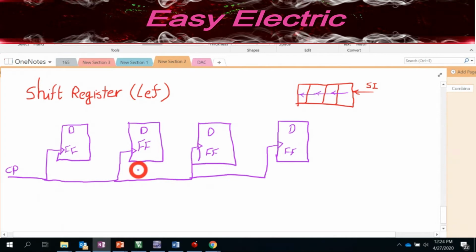So what we need to do for each of these inputs, so the D flip-flop has one input. Whenever there is a rising edge, if this is 0, the output will be 0. If this is 1, it should be 1. Somehow it keeps whatever you give as input, right? Based on what you want to design, the serial input should be entered from the most right one. So definitely you should put the serial input from here, which is the new one.